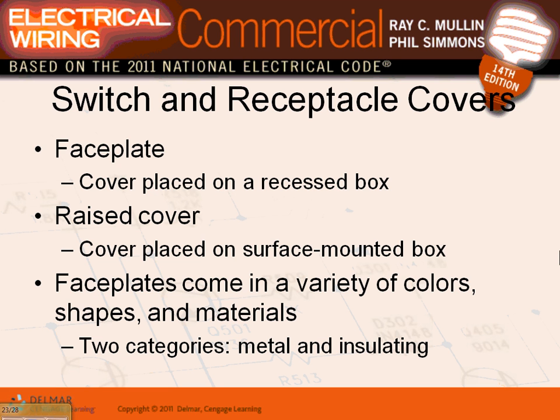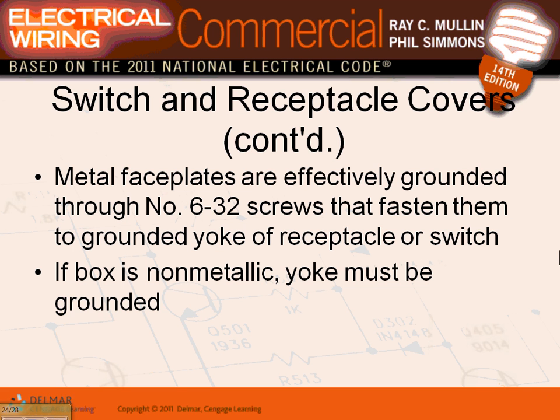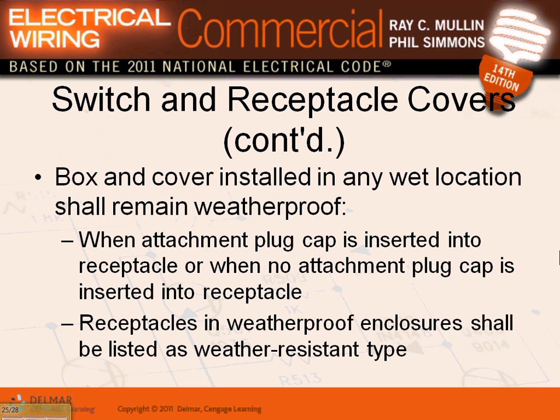Switches, raised covers, and so forth. This is just about the grounding of metal. This is just telling you guys about the size of the screw that you need to use to make sure that the receptacle is grounded, and you do not need to pigtail the receptacle or the switch to the box. So metal faceplates are effectively grounded through the screws that fasten them to the grounded yoke of a receptacle or a switch. The box and metallic yoke must be grounded. Of course, the box we ground through the conduit or the cable.